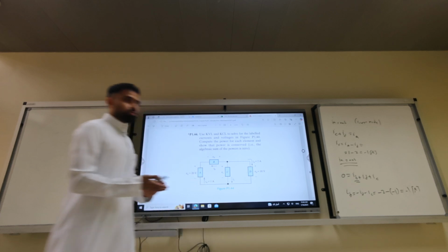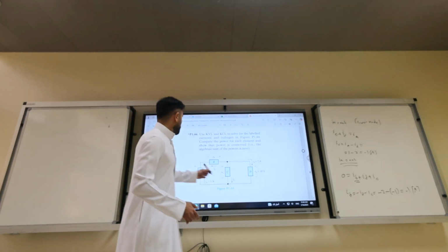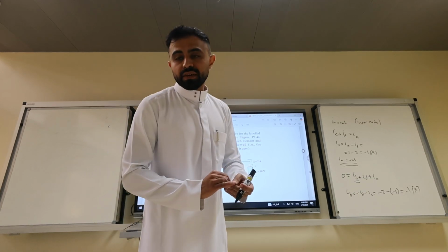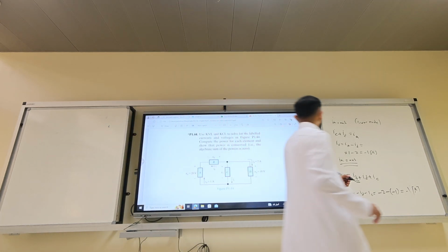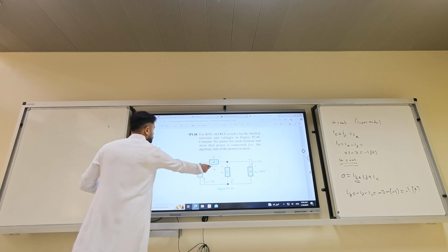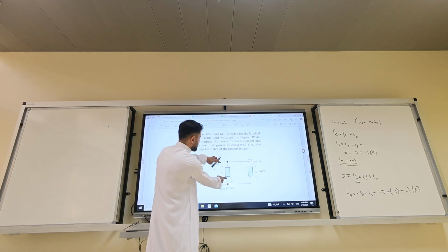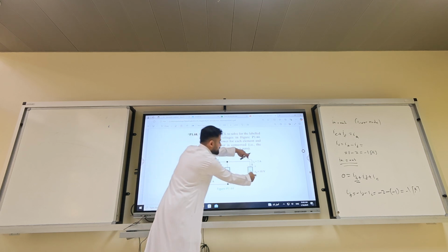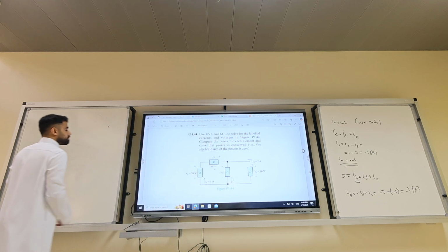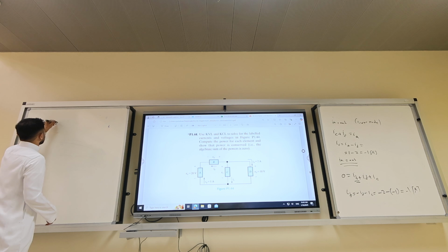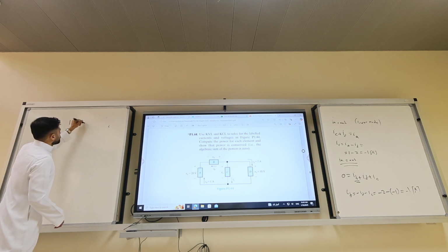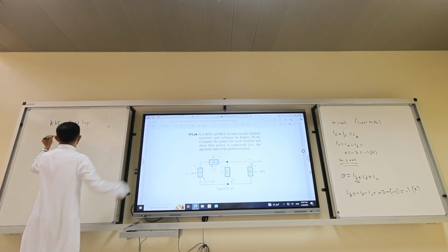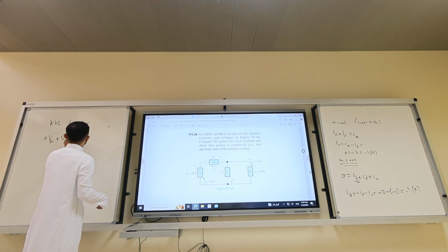Now once we calculate this, we can do a KVL. So IA is 1, IB is the negative of it. Now let's do a KVL. Which loop do you want to go through? This loop. You know VA. What is VC? VC is 10 volts, in parallel, with the same polarity. So let's do the left loop, voltage rise, KVL. You have plus VA, plus VB, minus VC.